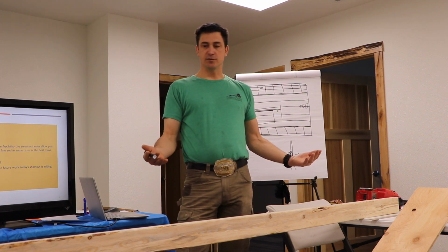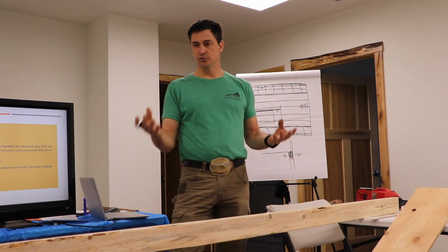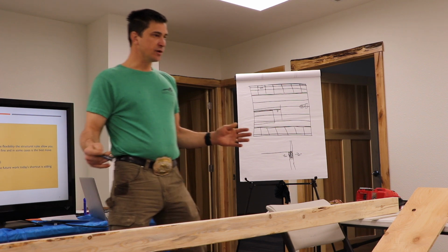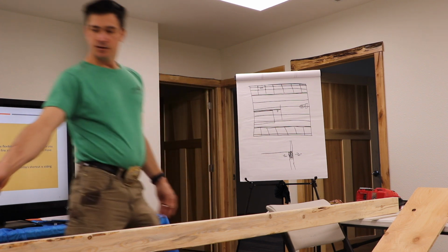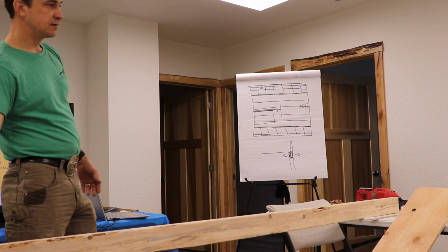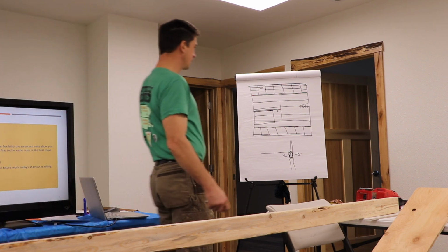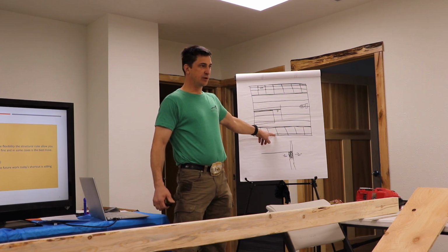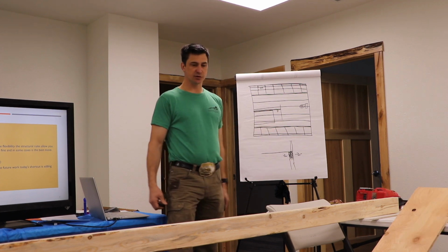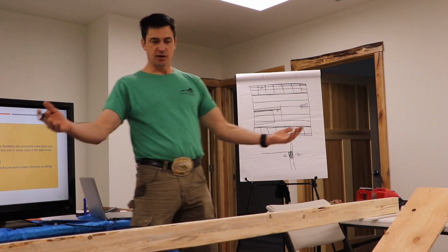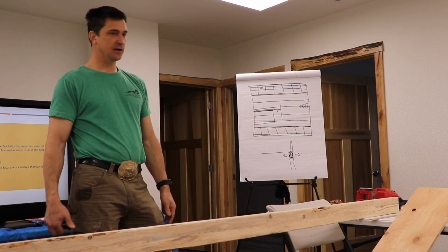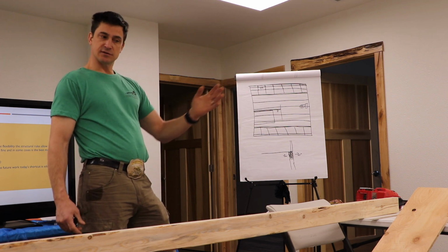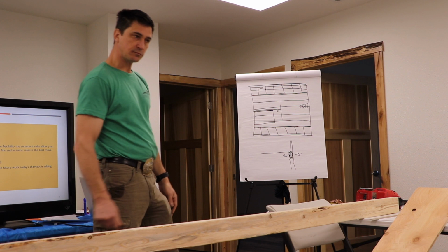That's why I want to give you guys a big picture and a bunch of tools, because I want you to be able to show up on a job and be like, wait a minute, if I slam the floor joist into this rim board right there, when my electrician shows up, he's going to have a pain in the butt time to get his wires run. When my insulator shows up, he's going to be like, what kind of an idiot would frame a dead cavity that I can't get to? And so I can use this solution to solve this problem.